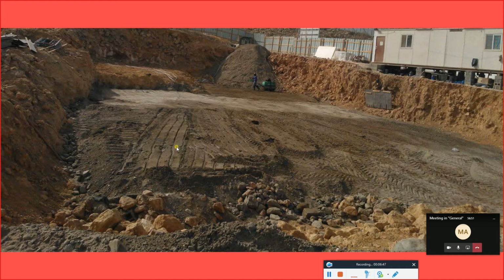Now, different equipments are required for the excavation. It depends on the nature of the soil. So if you have rock, you cannot use the same equipment or the same machine or the same excavator that we are using normally for regular soil. So it depends on which area, and that will help you in deciding which machine you are going to use. Anyhow, we are not going to cover the machinery, but this is just general information for you.